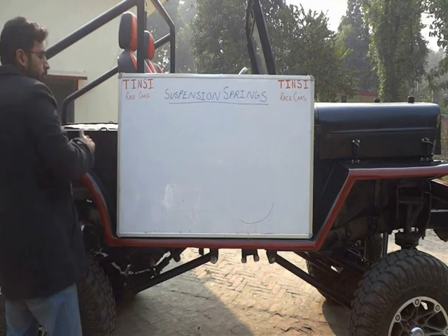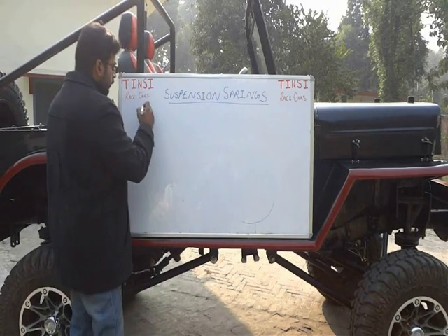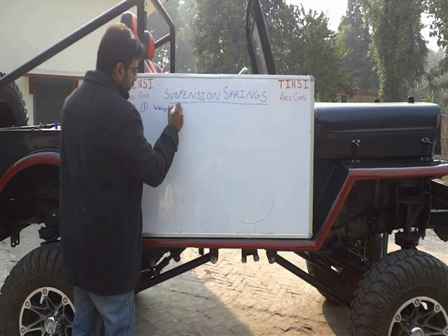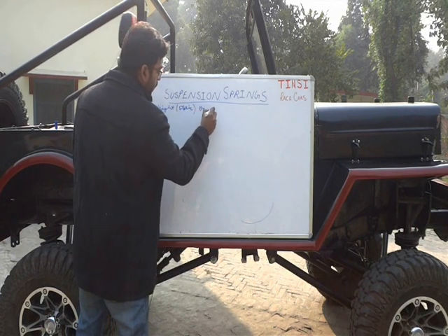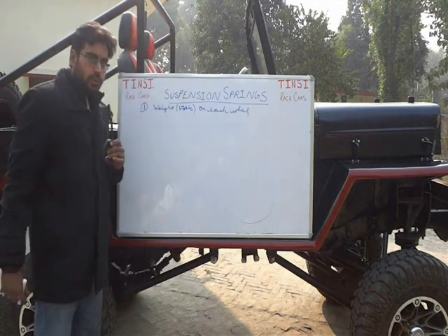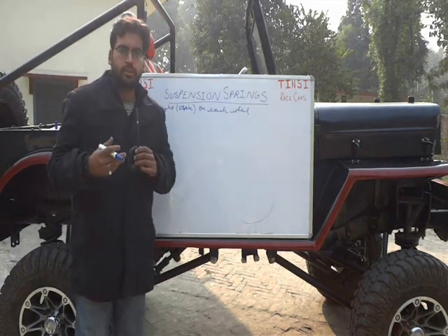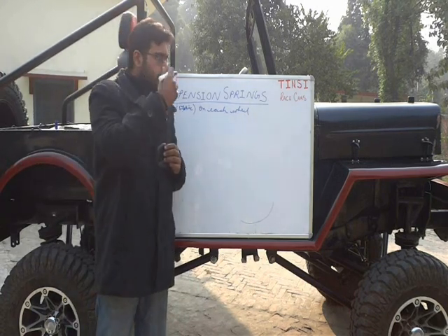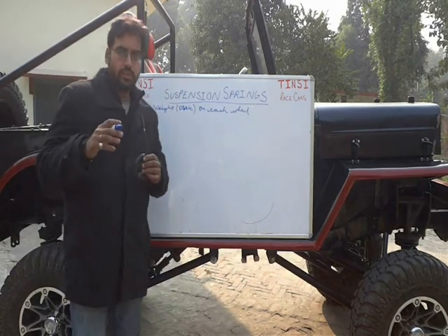So now let's go into the vehicle parameters that you need. First what you need is the static weight on each wheel of your vehicle. You have to measure everything, the engine, the chassis, all the small components, and then write down the weights on each tire. For this you basically need the CG location.